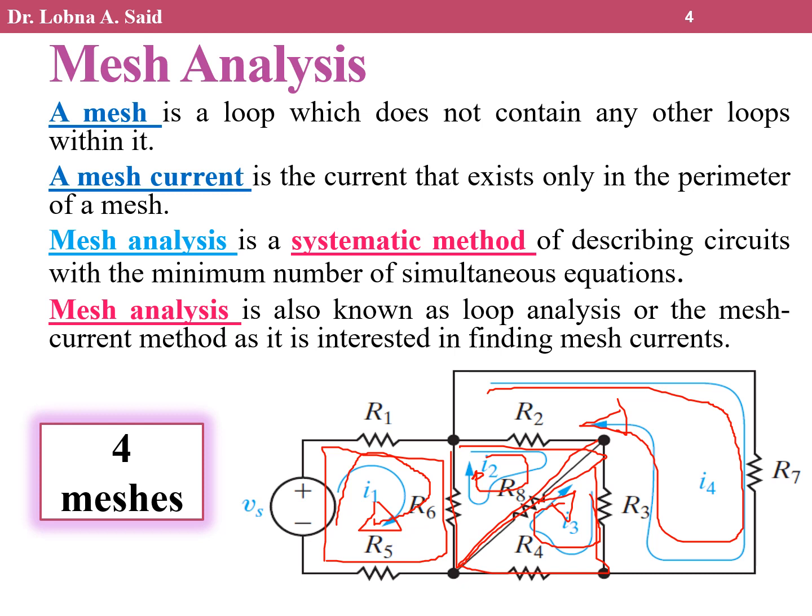As we agreed in the last lecture, nodal analysis has predefined unknowns. This is unlike KCL and KVL, where each one of you has to define your own unknowns. But in nodal analysis the unknowns are defined, which are the node voltages. So the node voltages are our unknowns that I'm trying to identify or obtain.